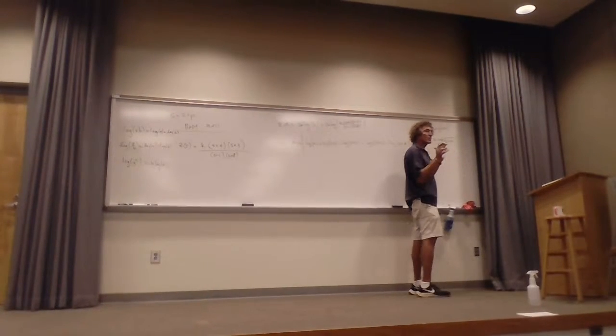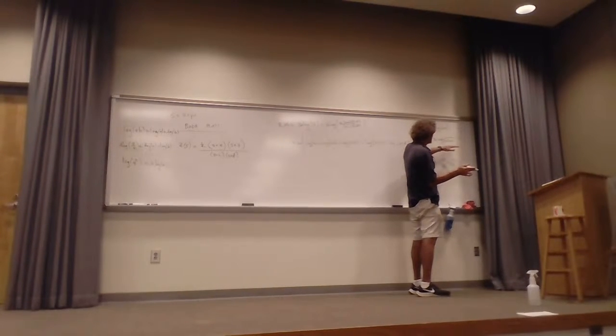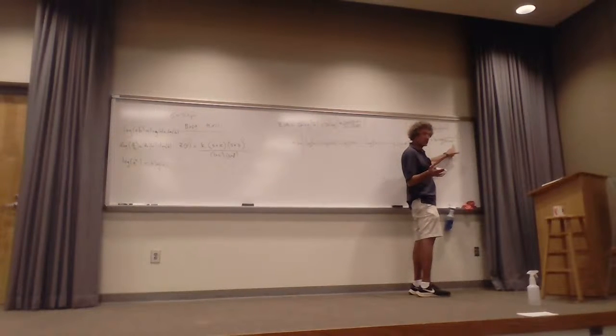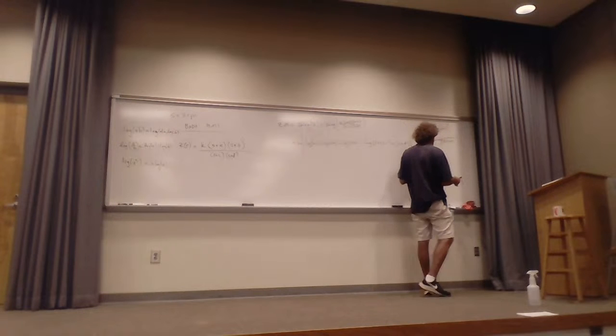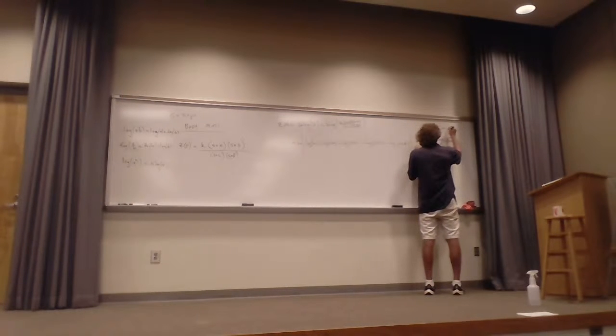Now, I'll show you the normal way of doing things. You may see something like this in a book, and they're going to say that the value of this when omega is much, much smaller than a is just 20 log of a. That's one thing to do. What I like to do, and I think this is the way it's taught in your signals and systems course, is I'll start here and I'll divide everything by that a.